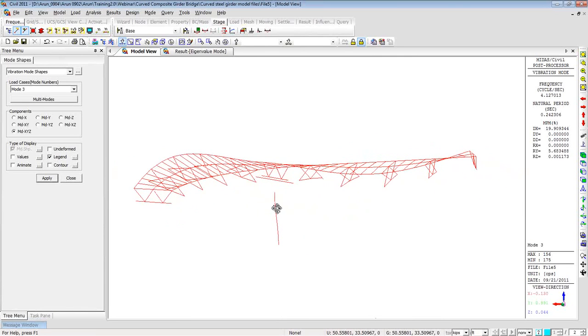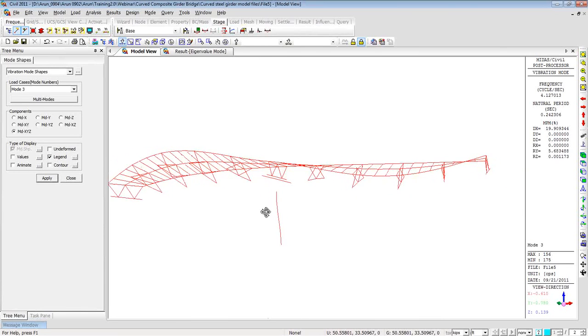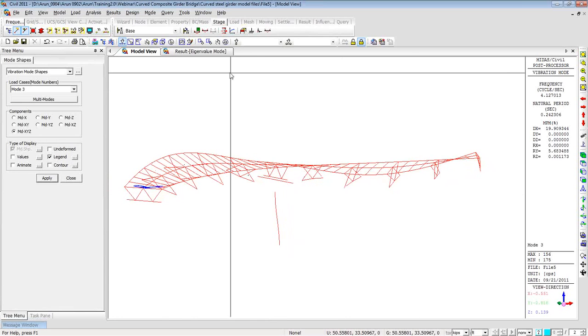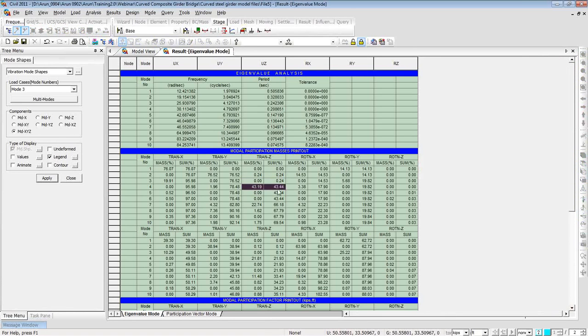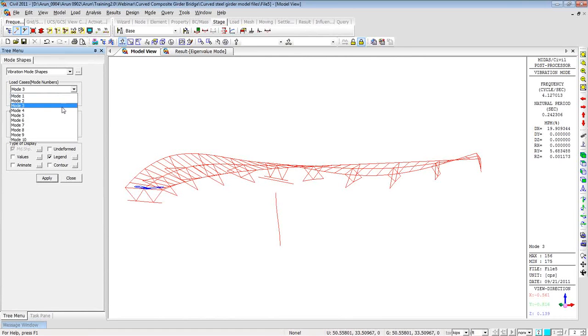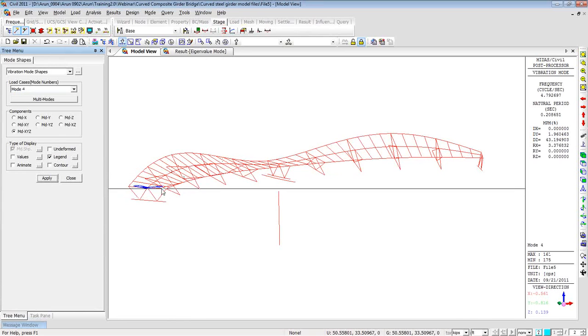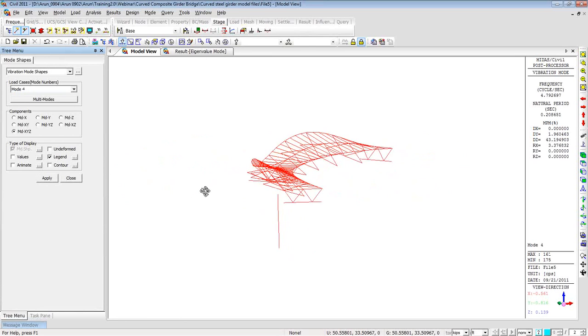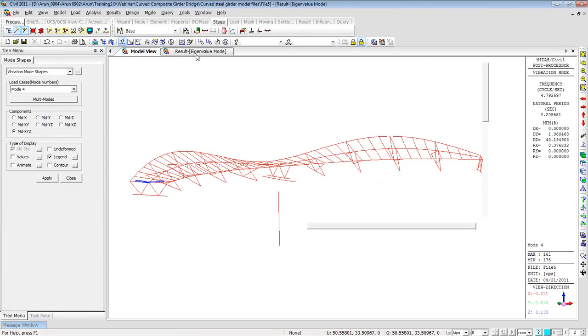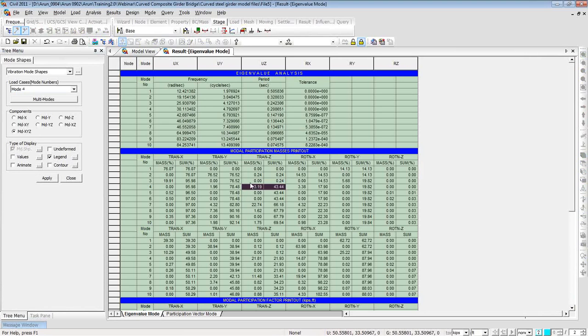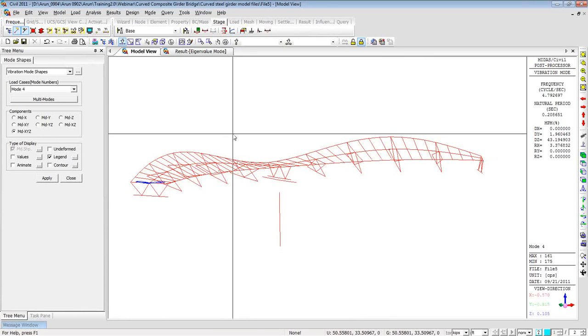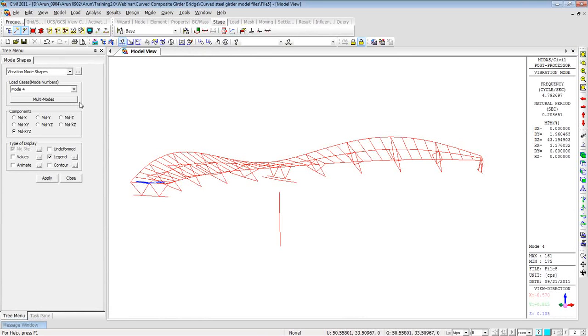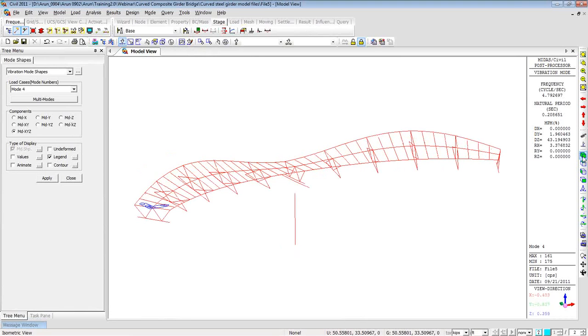So if I were to choose the principal mode shape for Z direction, I would have gone with the results for this mode shape instead of going for the fourth mode shape, which will look like this, as most of the mass is above the neutral axis, so you're getting a good mass participation value. So through this visual interpretation, you can make out which happens to be the critical mode shape or the principal mode shape for a given axis. And this is where the software has its advantage.